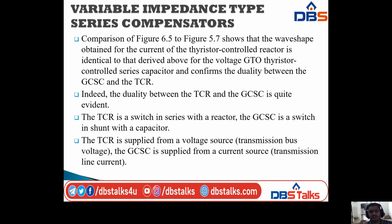So indeed, the duality between the TCR and the GCSC is quite evident. The TCR is a switch in series with a reactor, and the GCSC is a switch in shunt with a capacitor. The TCR is supplied from a voltage source, and the GCSC is supplied from a current source. That means in the TCR we are using the transmission bus voltage, and in the GCSC we are using the transmission line current.